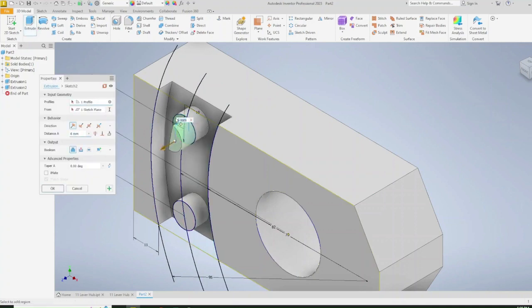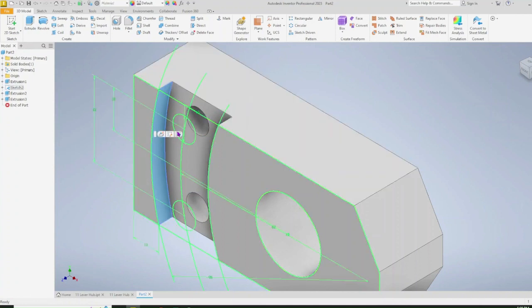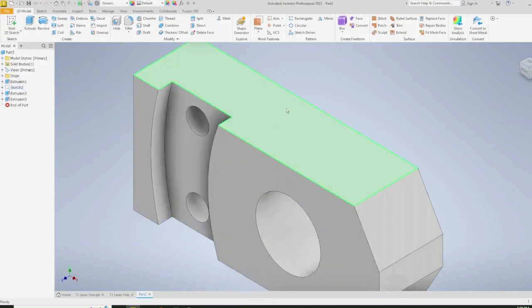So because I want to cut out this circle and this circle and cut it all the way out, I can by reusing that sketch or sharing that sketch. And once I say OK, there it is, and I can click back right here and turn off that sketch that says Make Sketch Invisible. And there, I have created this feature.